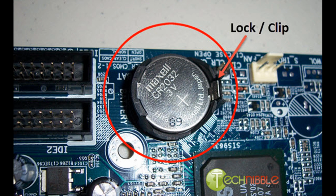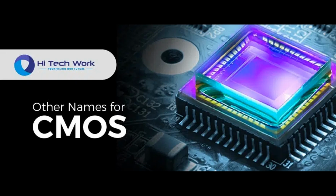The basic structure of a CMOS integrated circuit consists of individual MOSFETs, metal oxide semiconductor field effect transistors, arranged in a complementary fashion. Here's a breakdown of the basic components. Substrate. The substrate is typically made of silicon, upon which the MOSFETs are constructed. It can be either P-type or N-type silicon, depending on the specific requirements of the circuit. Source and drain. These are the terminals of the MOSFET through which current flows. The source is the terminal where current enters the transistor, while the drain is where it exits.